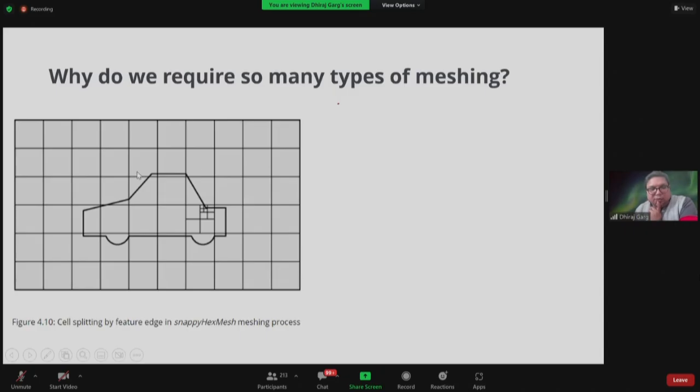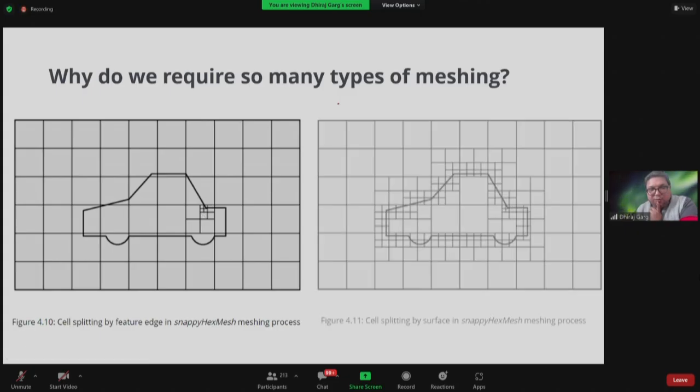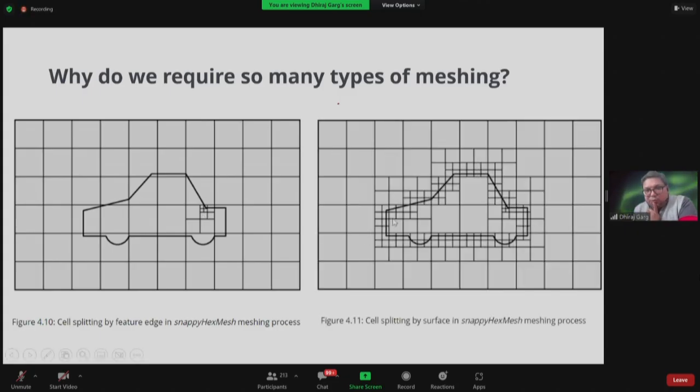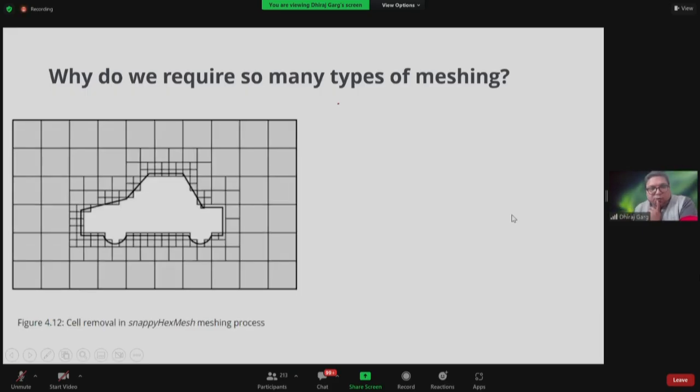You can see now, when we have a structured grid, then to cover this, we start with the grid, the cells, small cells, larger cells, and all that. We try to cover every part of the geometry. So for doing the procedure, we create more and more cells to cover the boundary. The very basic idea is that wherever the curvature or the gradient is large, you require smaller meshing.